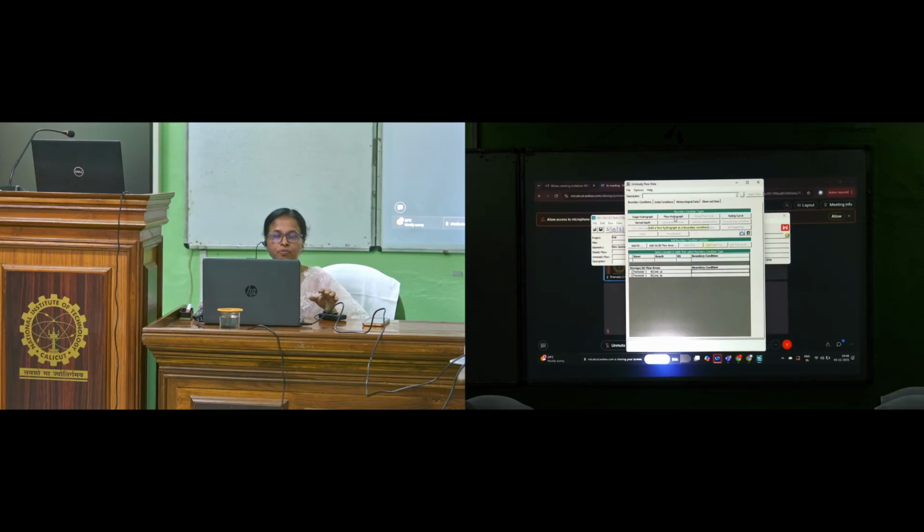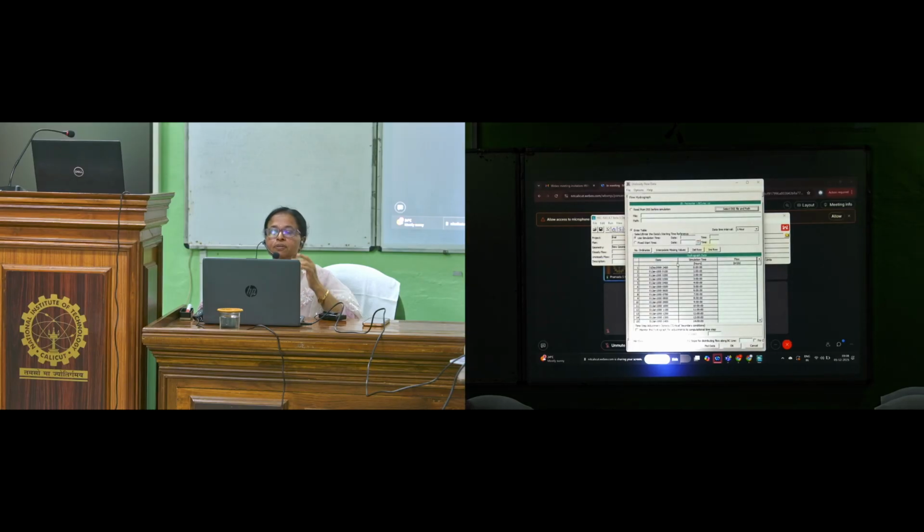This is the outflow. Yesterday you saw how to develop a hydrologic model. Usually you have to get the output hydrograph from that and input it here. Okay, so now I am giving random values. Here you have to give the date.